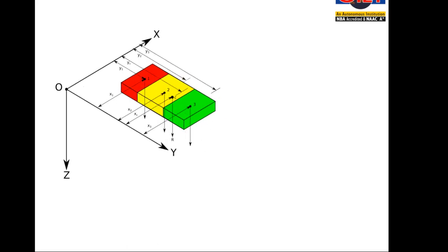This picture shows x and y coordinates of each and every individual gravity pull on the elements 1, 2, 3 points, and the resultant of all those 3 forces is represented as R as shown in figure, and C represents the point through which the resultant R passes, and by definition that point is the center of gravity. XC and YC are the coordinates of that center of gravity.